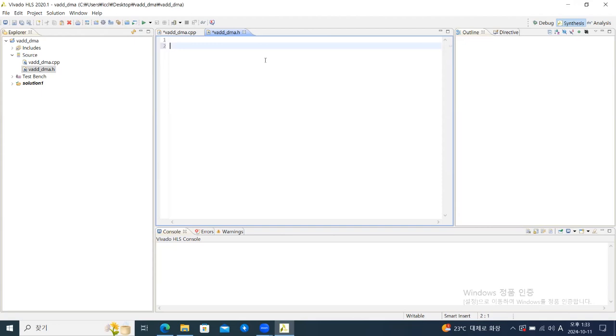Basically, the DMA not only sends the data itself, but it has extra signals called keep, last, and valid, and so on. If you remember the block level diagram, we had additional signals such as address, ready, valid, and in case of DMA, we have more signals, and most importantly, we need the keep and last signals to actually use the DMA. So let's start by defining our custom type for our AXI DMA interface.